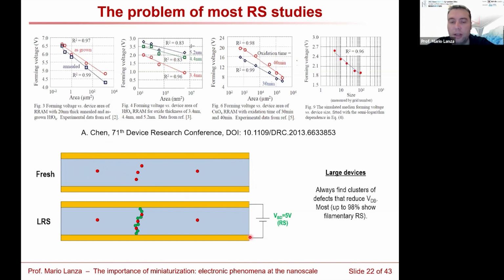When you apply voltage, you will generate a conductive filament at the weakest point of the sample, which will be at this point, okay? And this filament will have some properties. Now imagine you measure this device and you observe an endurance of 10 to the 12 cycles, okay? This is an excellent memristor. The filament has been formed in a weak place under a low energy, so it is reversible. It can be destroyed.